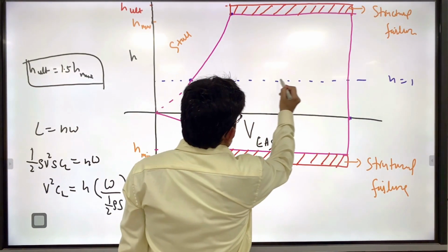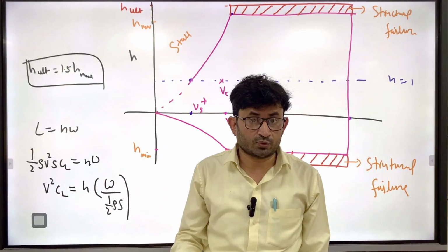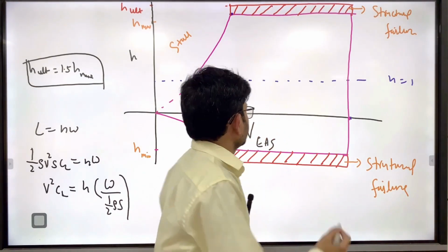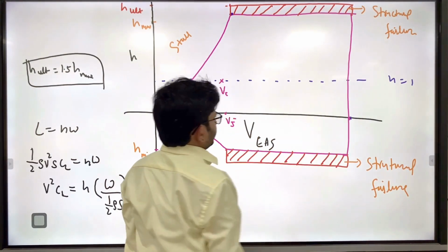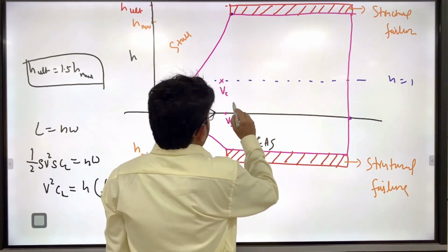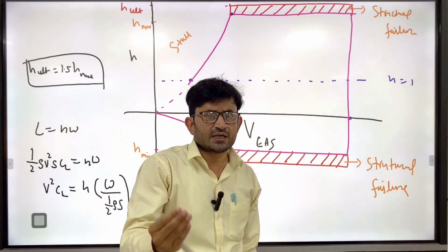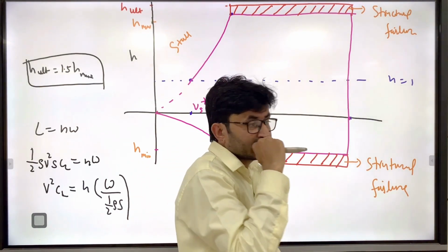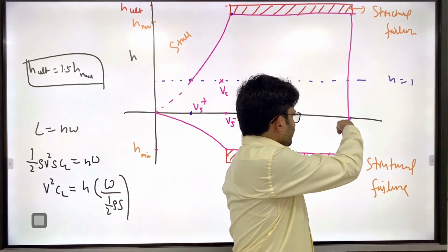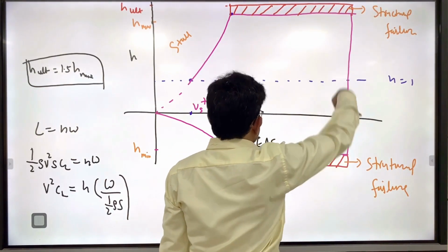So along this n equal to 1 line, you can fly at a different design speed, right? Sometimes it happens that design speed is 1.2 times Vstall, 1.5 times Vstall, or sometimes 2 times Vstall. So you can move along this line and fly at different trim flight speeds. Now you notice one point. Sometimes this maximum limit can be 2 times Vstall, 3 times Vstall, 5 times Vstall, depending upon how powerful the engine is. Okay, and sometimes it happens that your dive speed is more than the maximum allowable speed at a steady state level flight case. So depending upon that, you can draw this line.